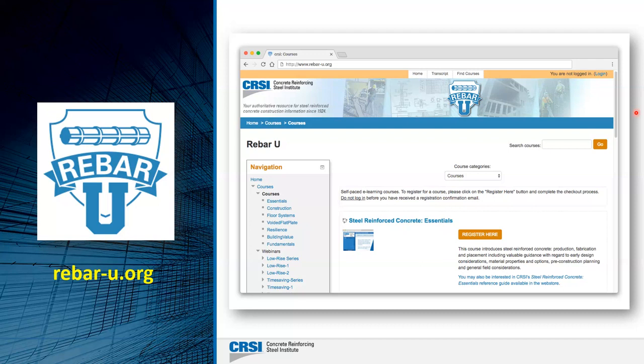Here's one question. Is it generally considered best practice to detail the slab to wall for both method A and method B to allow the contractor full flexibility in construction? Yeah, usually what I like to do is talk with the contractor to see how they're going to do it. They'll generally have that information available at the onset of the project, and then tell them, okay, this is the way we're going to detail it. And if you change it later, which they usually don't, be aware that this could be an extra service.